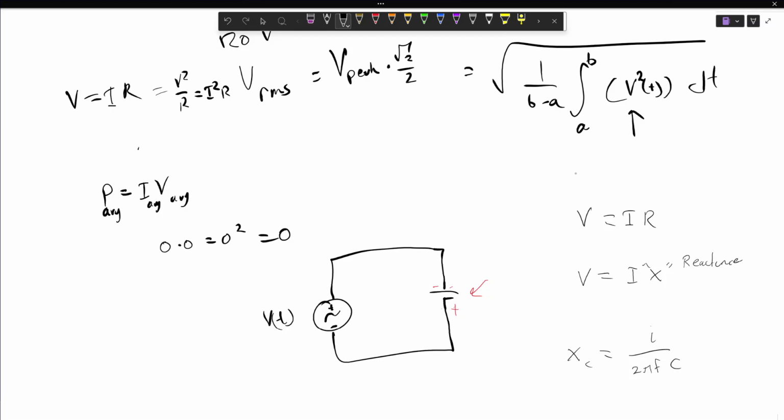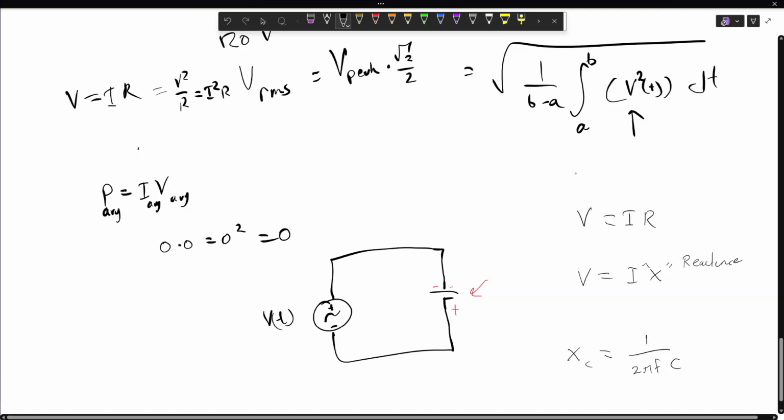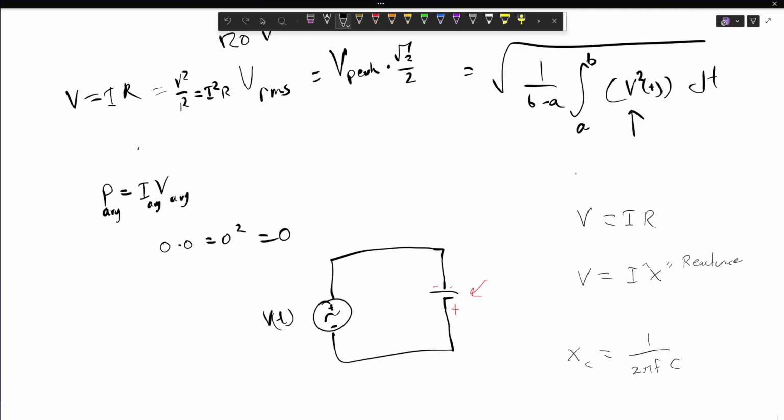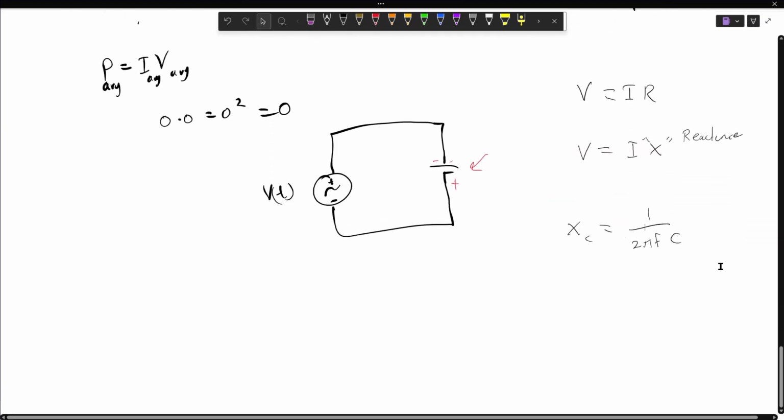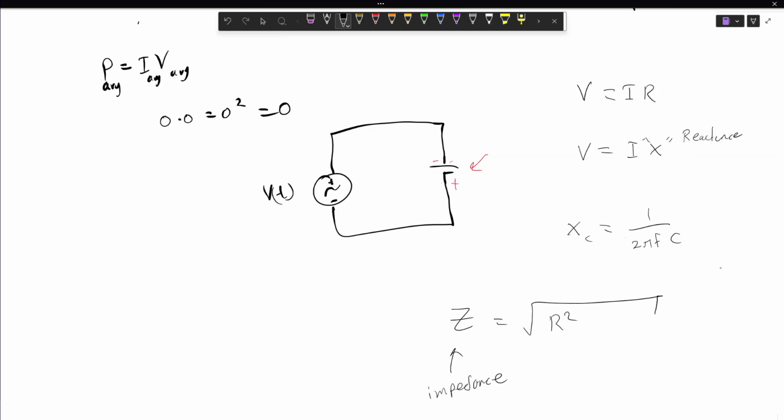Technically, there's an imaginary number here. We'll not worry about that. Actually, even super technically, it's like a 1 over negative. We'll talk about that later, maybe a little bit in detail. But at some level, what we do to find a net resistance, a so-called impedance, that was kind of why I injected that word earlier, we call this total impedance Z. For reasons we'll find, it looks like the Pythagorean theorem, where we take the reactance squared, add it with the resistance squared, and then square root it. So resistance, reactance.